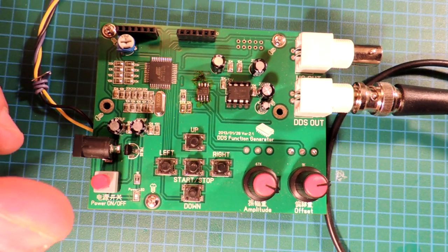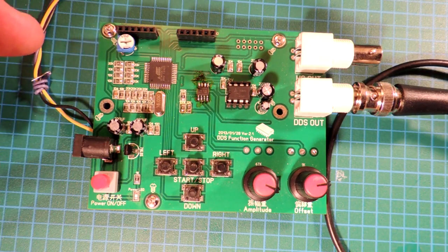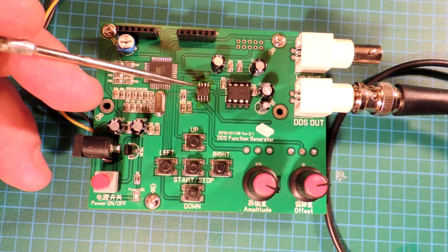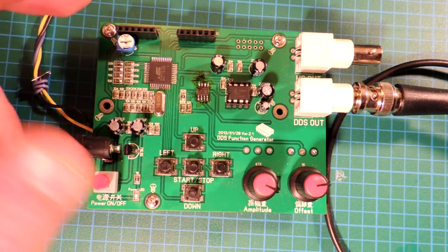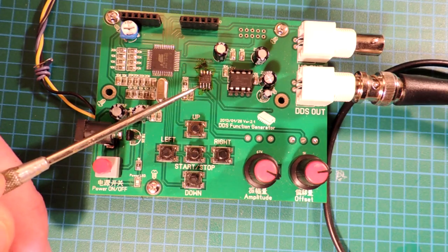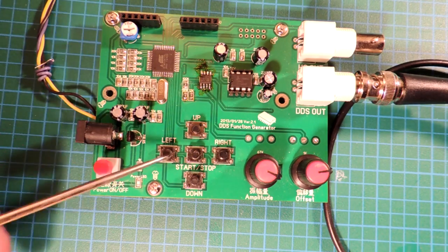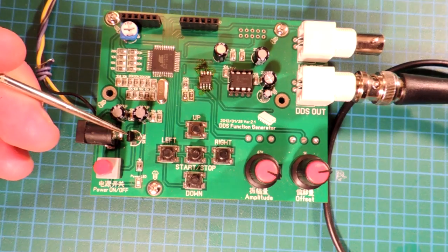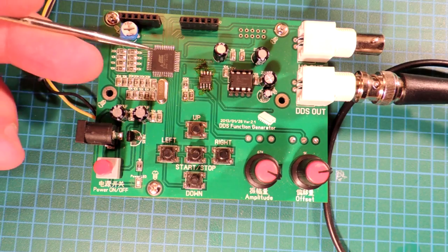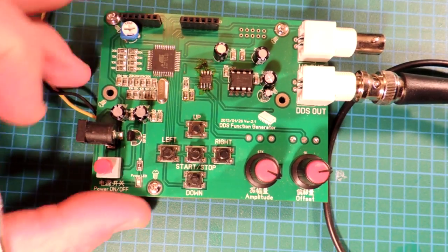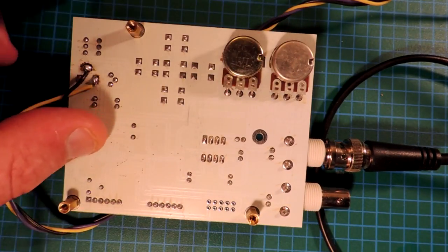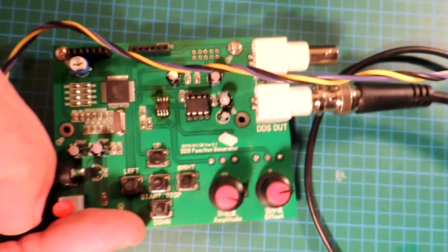This thing can go to like plus or minus 14 volt outputs, but when you run it to a 50 ohm input on a spectrum analyzer, you can really quickly overload the poor little op amp, and it blows out. Again, it's just an op amp driving out to the BNC. There's no decent push-pull stage on it. A little keyboard here, of course. The input has a 78L05, so you feed this thing like 9 volts, and it gives you the 5 volts, which I'm sure goes to the processor. The back is completely unpopulated, other than the two potentiometers for the voltage control.